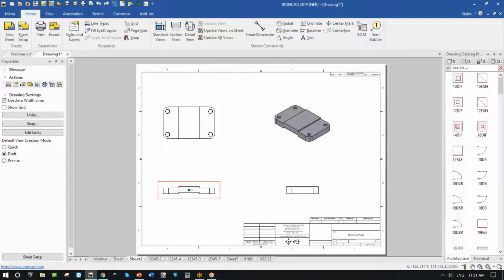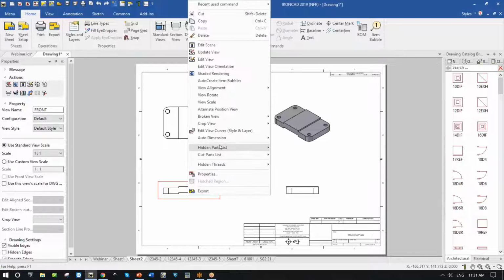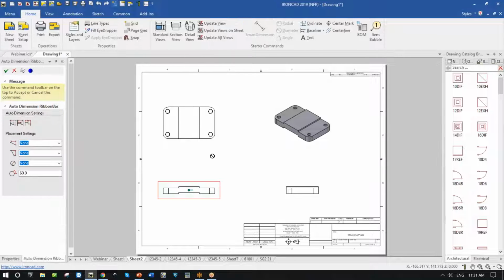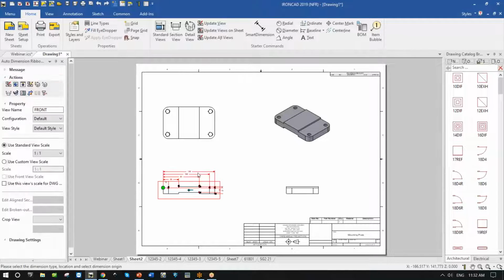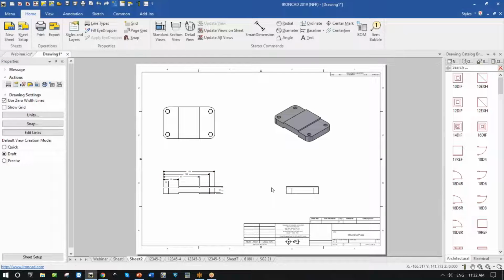And by the way, things like, oh, I need some dimensioning. So go ahead and dimension this view. I'd like to use dimension from a particular line, give it above and to the right. And I've decided today that this is going to be where I want my 0, 0 on this particular part, pardon me. Go ahead and accept that. And very quickly, I get all of these dimensions.